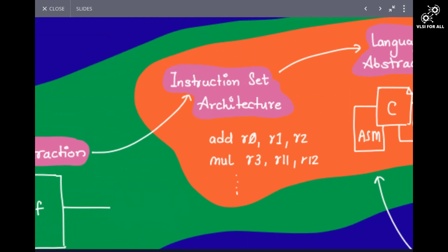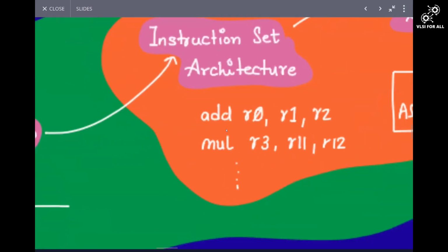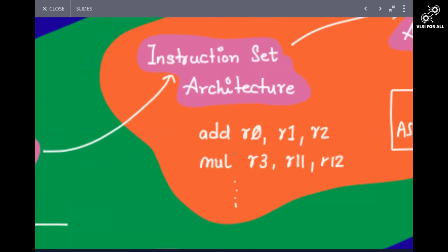So within the 8051 microcontroller, there is a processor, the CPU. The atomic operations that are performed by this CPU are called instructions. So for any processor, the language that it understands is its instruction set, right? For example, you have a separate instruction for add, and a separate instruction for mul. If you pass this add instruction to the instruction pointer register within the processor, the ALU will perform addition.